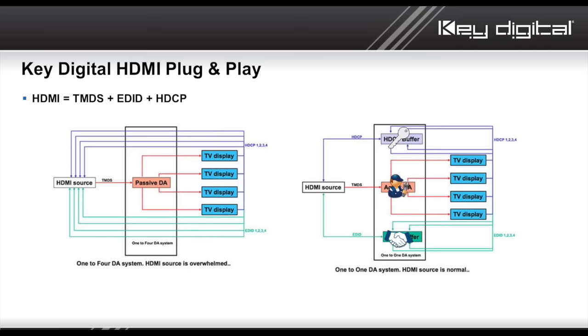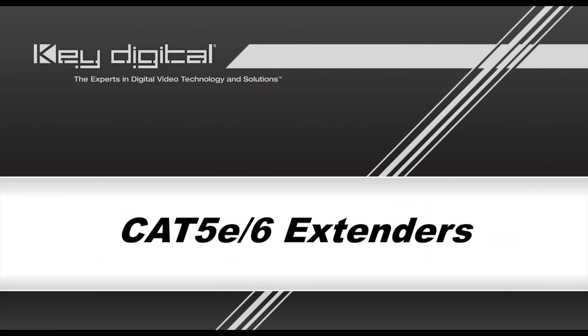TMDS, oh, that signal came in rather lousy. Let's reclock that signal. And EDID handshake, providing the source with its information of what it should output, source complies, or even asking the connected display, what is your handshake, so we can be more accommodating to that display in the case of it being very old or very new, who knows. We can ask it what it wants and tell the source that it should output that.